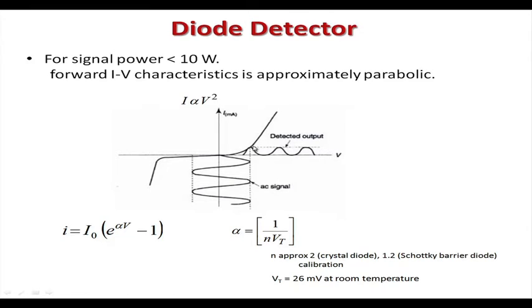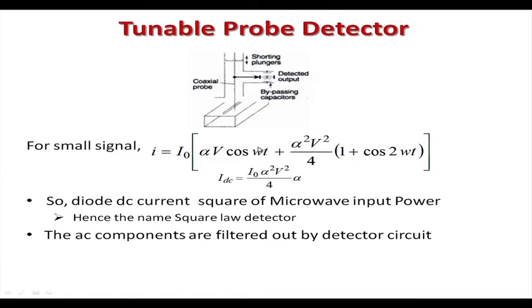So, if you want to measure the signal precisely, we have an experiment in our lab, the calibration of these. Basically what we do with the diode, we vary the voltages and note the currents in an ammeter and plot this graph, and from the slope of the graph we find out the value of n. Now, typically in our labs we get 2.2, 2.3 in that range, but obviously it is voltage dependent. So, for a particular source you can always calibrate the diode, that gives accuracy to the detection. Now, this is what I was showing.